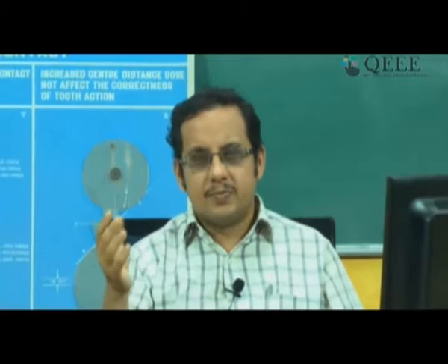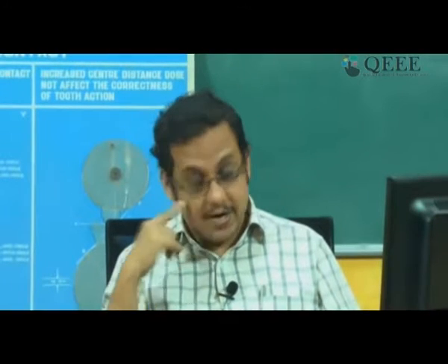Okay, the last question that I have is, which profile has the least pressure angle? See, we are talking about the involute tooth profile. Involute tooth profiles can be made with pressure angle 14.5 degree, 20 degree, or 25 degree. We are not actually comparing different tooth profiles at this stage. In fact, as I told you, it is difficult to make that comparison because pressure angle is not constant for other tooth profiles. The pressure angle happens to be constant for the involute tooth profile, and the standard pressure angles in which mass produced gears appear are 14.5, 20 degree and 25 degree.